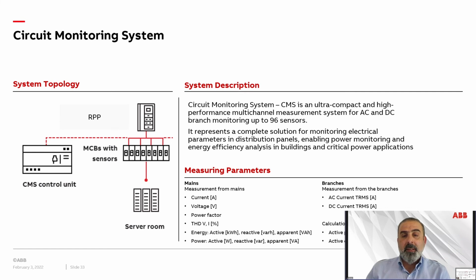It provides efficient energy management. It's easy commissioning with integrated web servers to teach sensors and visualize the measurement, so no external software is needed. It works for AC and DC, mixed current, scalable, flexible, and it ensures maximum data security because it's end-to-end encrypted communication with SNMP version 3. Protocols like RS485 and RJ45 allow integration to higher level control system.